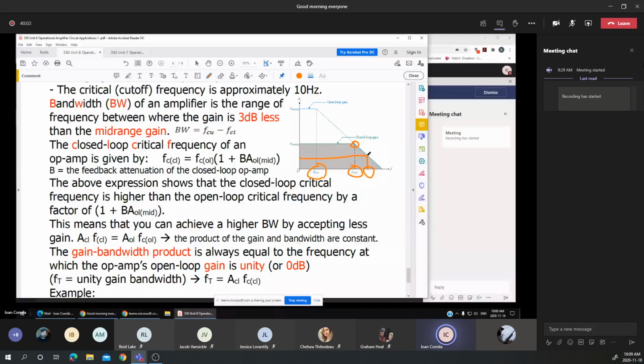Now, if the frequency is not a concern, we may use a pretty large gain, but again, it depends on the input frequency, or on the signal. The most important part is to always look for a constant gain, and try to find what the specs or requirements are for the frequency of the input signal.